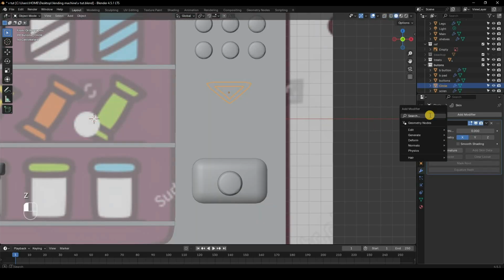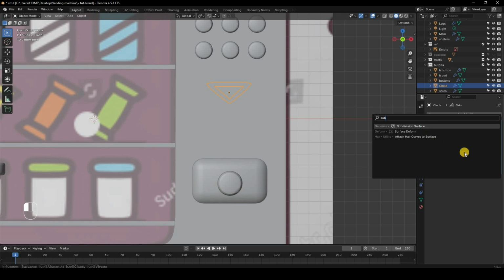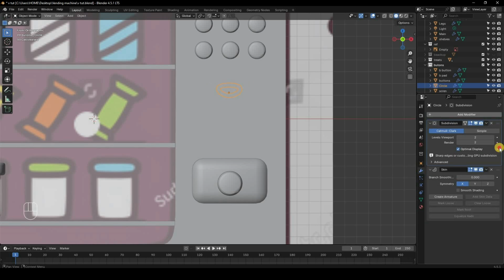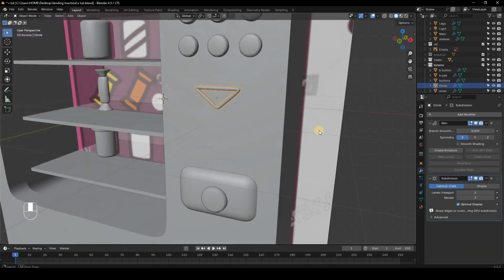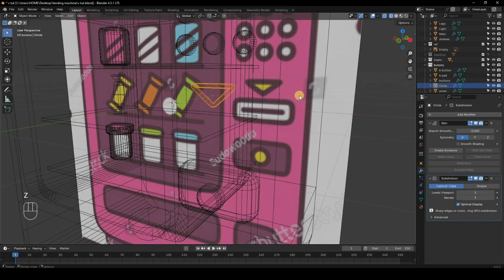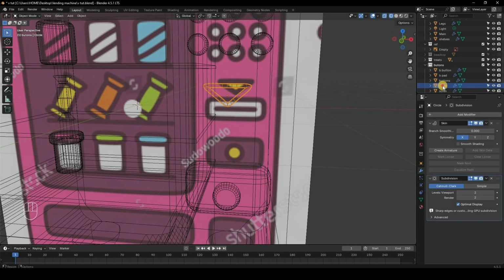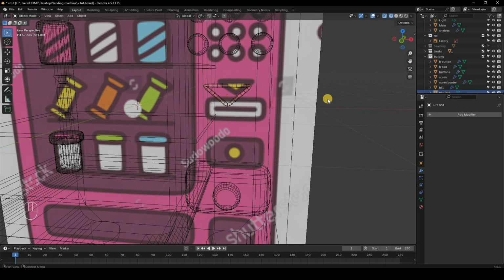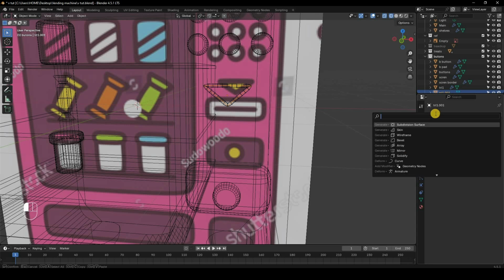and maybe give it a subsurface modifier. Yeah, I think this looks a little bit better. Yes, definitely this one looks better. So now this is the circle for what I'll call try 1. I'll also Shift D and duplicate it, remove the skin and subsurface modifier, tab into edit mode, click on F to fill the face, and I'll add a solidify modifier for it.